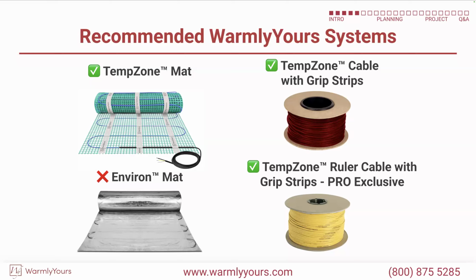So tell us about these different products and how they work with the LVT. Okay, so my favorite choice for LVT, LVP products, anything you're going to self-level, I like to use the TempZone Flex Mat style system. What's beneficial about this is it's super low profile and the wires are already attached to the netting, so it unrolls very easily.